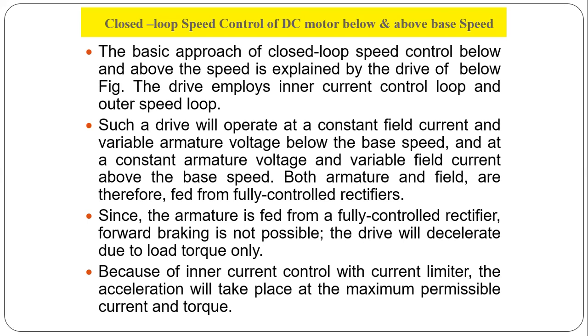The drive will decelerate due to load torque only. Because of inner current control with current limiter, the acceleration will take place at the maximum permissible current and torque. So according to that, we can see in the next slide how it is operated.